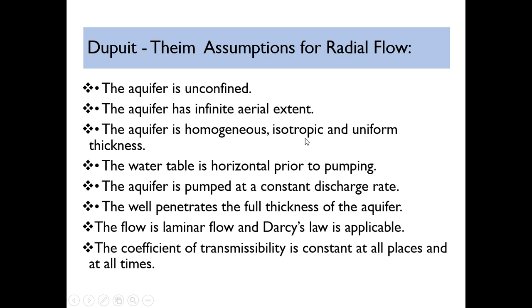Isotropic means permeability is the same. The water table is horizontal prior to the pumping. The aquifer is pumped at a constant discharge rate. Pumping is with constant discharge. The well penetrates the full thickness of the aquifer.